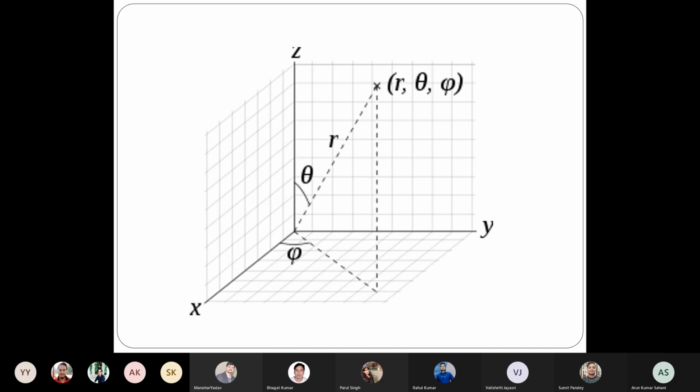Okay. So these principles are combined in the total station, where when you point at a particular target using the total station, internally this XYZ coordinate system is defined, and then a laser beam is fired that hits that target point P1, and that range R is measured. Similarly, the total station also measures the two angles theta and phi. So R, theta and phi, these three parameters are computed, and then you can further estimate the coordinate in the Cartesian coordinate system.